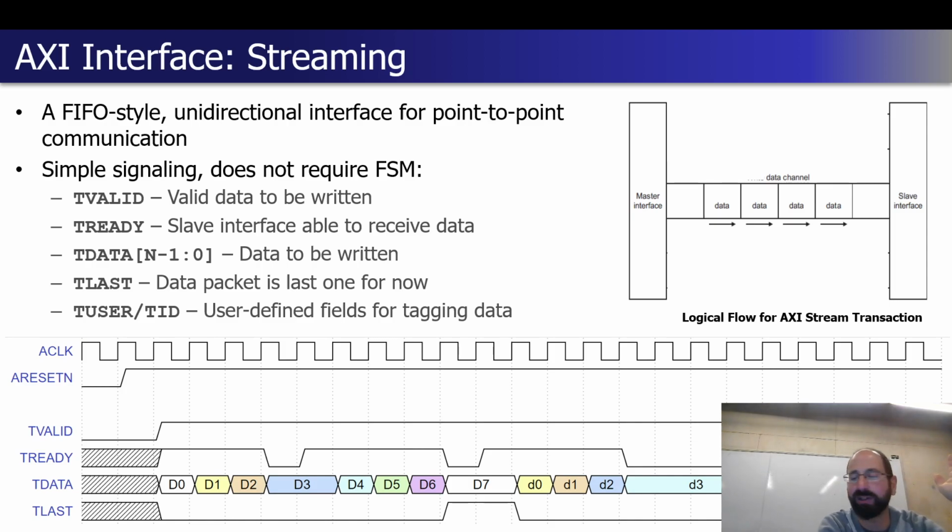There isn't one magic way that says, here's how you specify that you are done sending or done processing something. This TLAST signal is one way we can do it. Other ways are by having some configuration register in your IP cores where software tells you that it's done. Other times we just have convoluted sets of counting variables where we specify you're going to do this much work, you tell me once you've done this much work, and I will monitor when you are done. But you're going to face this as early as MP1, where we have this double buffered frame buffer.